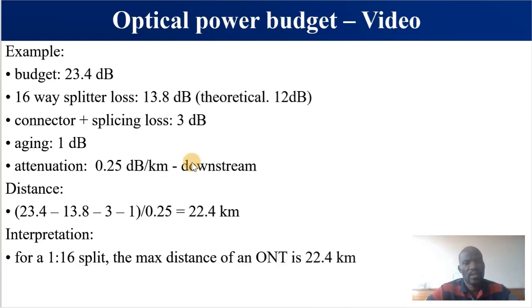To find the PON stretch, we are going to divide by the 0.25 dB per kilometer, so your PON can stretch for 22.4 kilometers. So please take note of the way you can calculate the PON stretch given this kind of data.